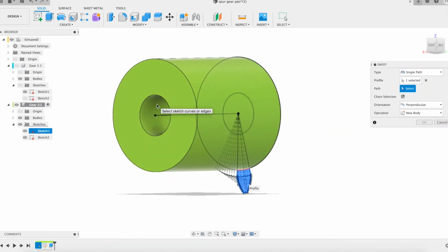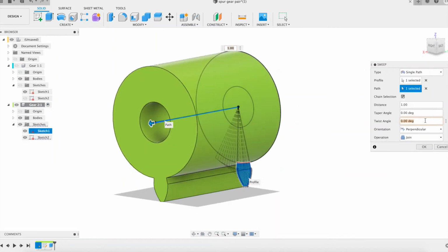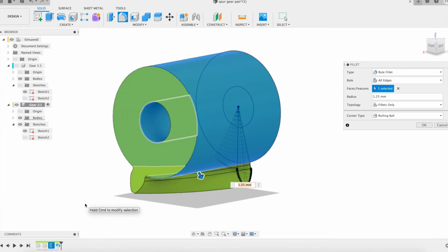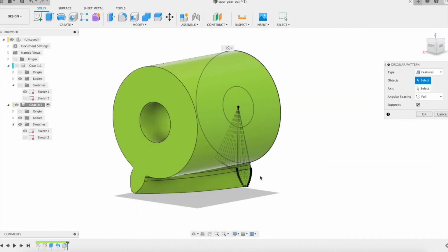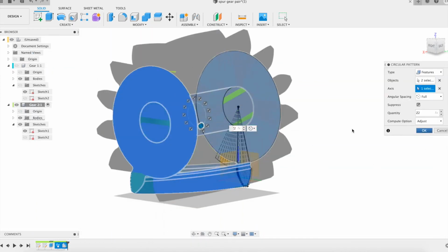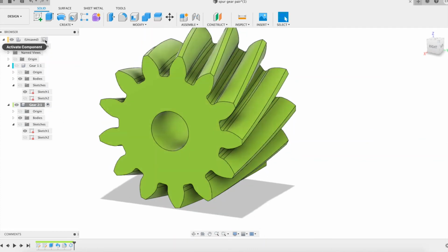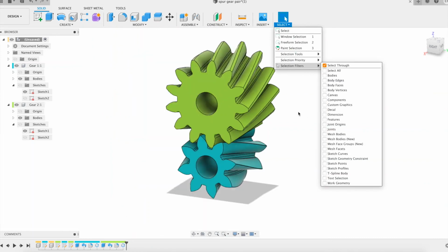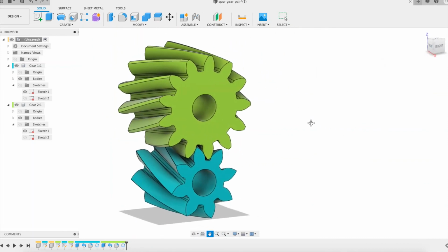The helical gear has some advantages over the spur gear. It has improved tooth resistance due to the longer support of its helically wound base, thus offering greater strength and increased load capacity. The axial tooth overlap also allows more teeth to mesh simultaneously, resulting in smoother and quieter operation. The free choice of the helix angle also allows, curiously enough, a certain flexibility in adjusting the center distance.